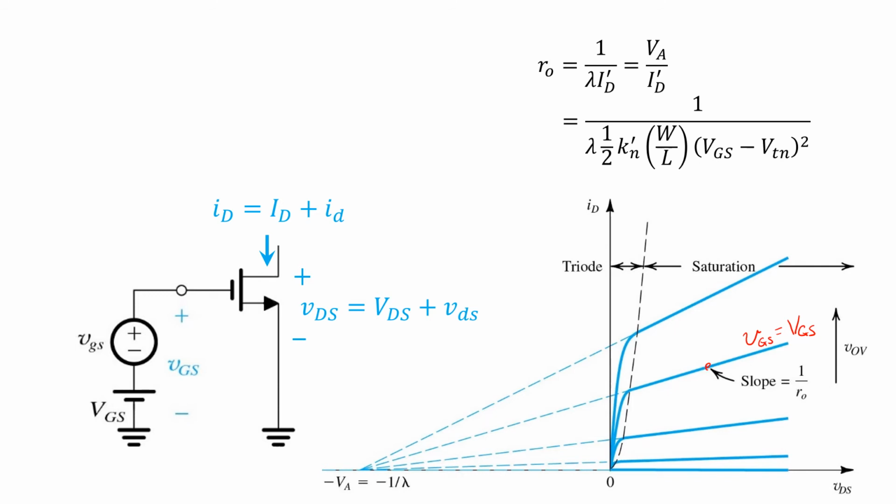And let's say the operating point lies here. That's the nominal value, or DC value, of uppercase VDS here. Then we know that with changes in VDS, even if VGS stays the same, we'll get small changes in drain current around its operating point value. So again, we usually denote the operating point with a Q, and this here would be our uppercase ID.